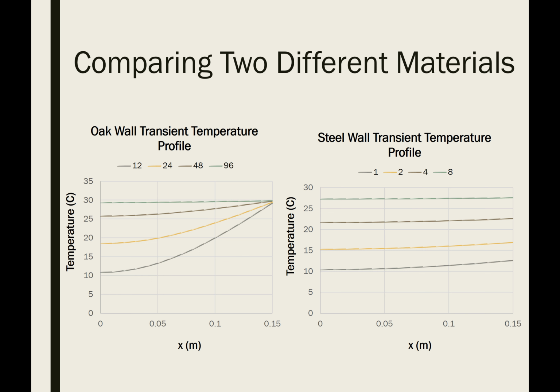In certain circumstances we might care about this, so there is still kind of a temperature gradient here. Maybe for some reason we want to know exactly how that temperature profile looks. But in general, we could just treat these as flat lines. By applying the lumped capacitance approximation, instead of using this one-term approximation to the real analytical solution, we would lose that information regarding how temperature changes with respect to x, but certainly losing a lot less information in this case relative to the other case.